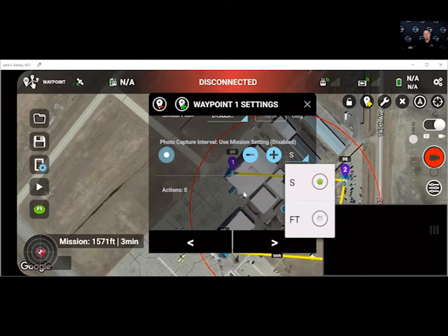So if, for instance, you build a facade mission, you've got a large high-rise that you want to do an inspection top to bottom, and you want to do lines up and down the facade of that, you would choose your speed of the flight of the aircraft along with the picture capture interval to match that speed and the abilities of your cameras.